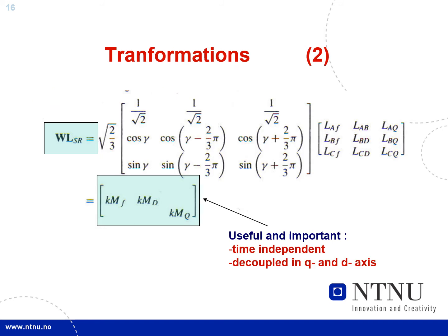Now, if we look at the mutual inductances between stator and rotor, we obtain those by the same transformation, and what we find here is that they are also time independent and as well decoupled in the Q and D axis.